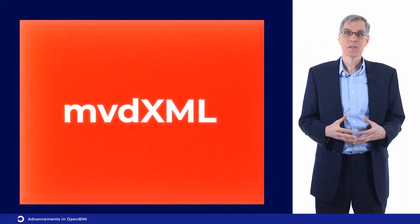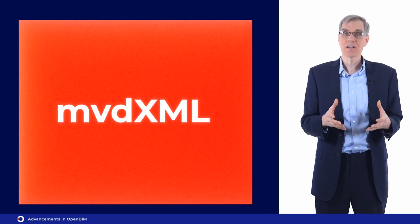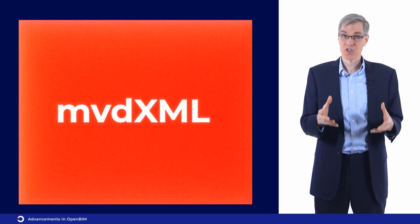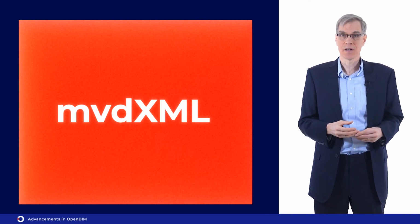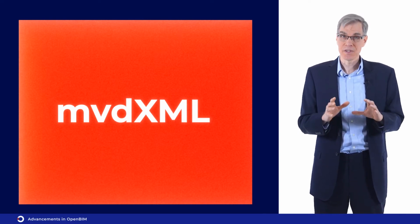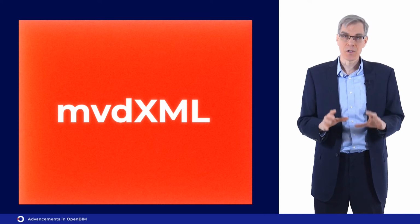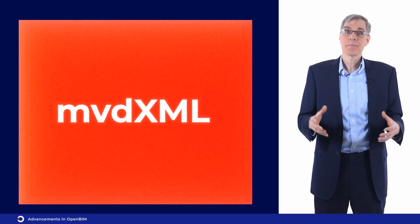In addition to IDS, ODA has also recently added support for mvdXML. A model view definition, or MVD, defines a subset of the IFC schema that is needed to satisfy one or more exchange requirements. MVDs are encoded in a format called mvdXML, and they define the allowable values at particular attributes of particular data types. mvdXML is often used to customize the export of IFC data. It's an older specification that was first published in 2013, but it's still in use today and is quite popular with some companies.